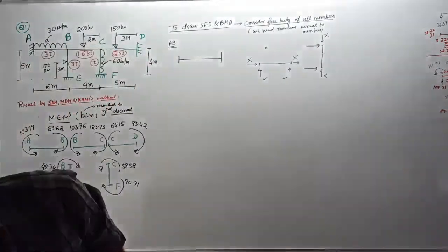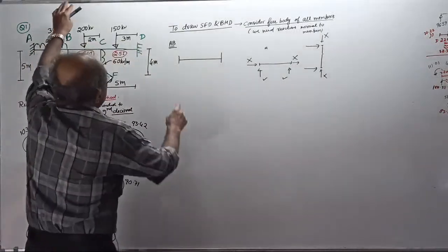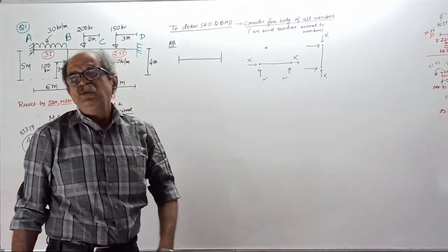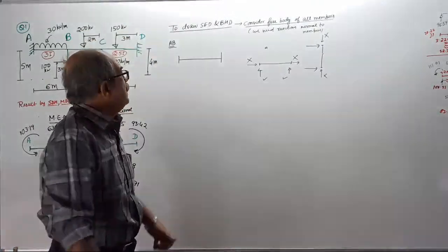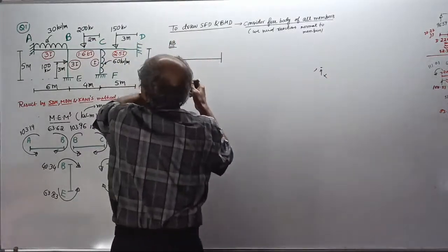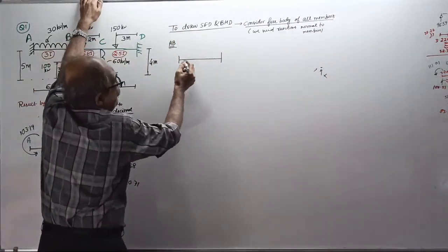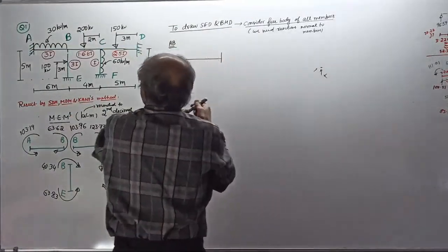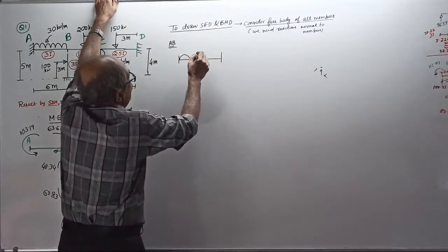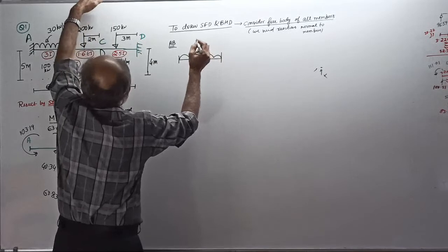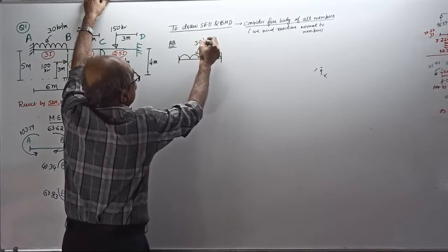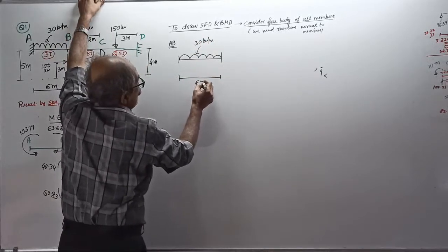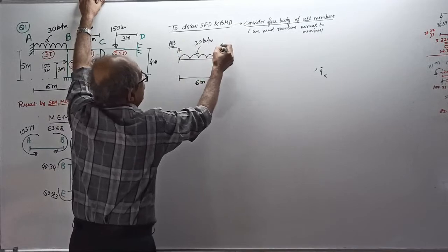Okay, start. Because someone will say, this is a fixed support, there is a horizontal reaction there, and he has not accounted for it. I will tell you, learn somewhere else, not from me. Okay, now start. First consider AB. AB is a horizontal member. For every member, this time I won't use color. Horizontal member. It has got a UDL. You have a lot of work today. UDL of 30 kilonewton per meter. Length of member is how much? 6 meter.